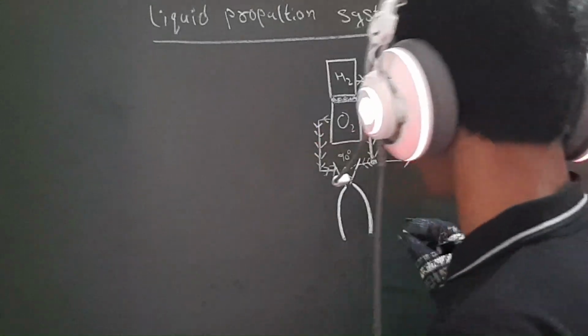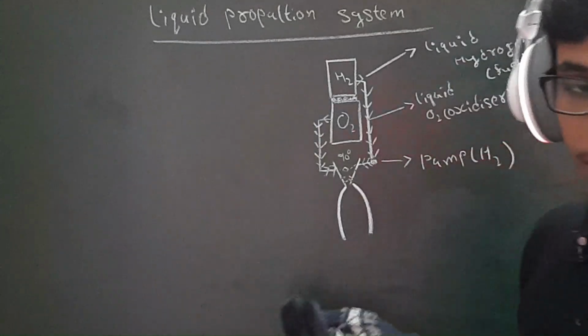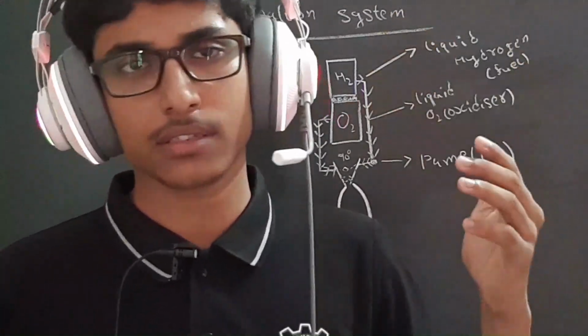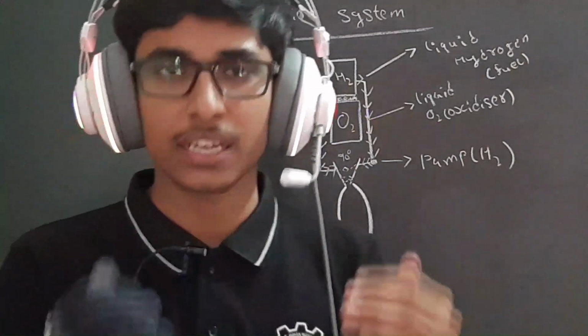So these combustion chambers have spark plugs which create sparks and ignite the fuel. And yes, the oxygen is used in both cases, when the rocket is in the Earth's atmosphere and when the rocket is leaving the Earth's atmosphere. This is because, to have stable flight performance, if we depend upon atmospheric oxygen supplies, the supply will not be constant: when the altitude of the rocket increases, the atmosphere gets thinner and thinner and the oxygen supply gets lesser.